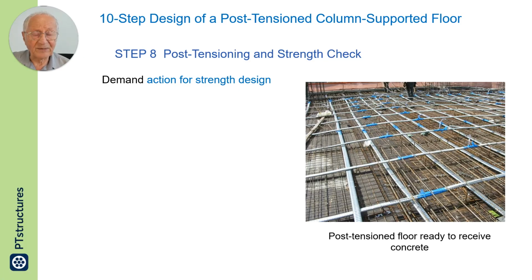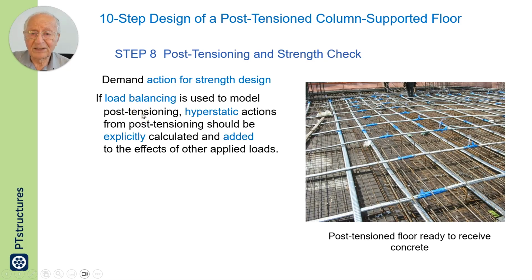After having gone through the minimum rebar, then we go into strength check. For a strength check, we need to know what is the demand moment, demand shear, and then we check the section to be adequate to resist it.